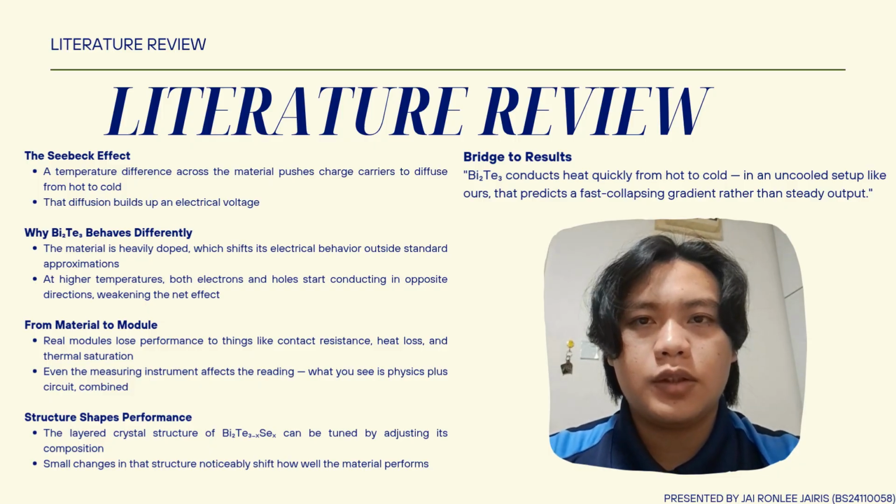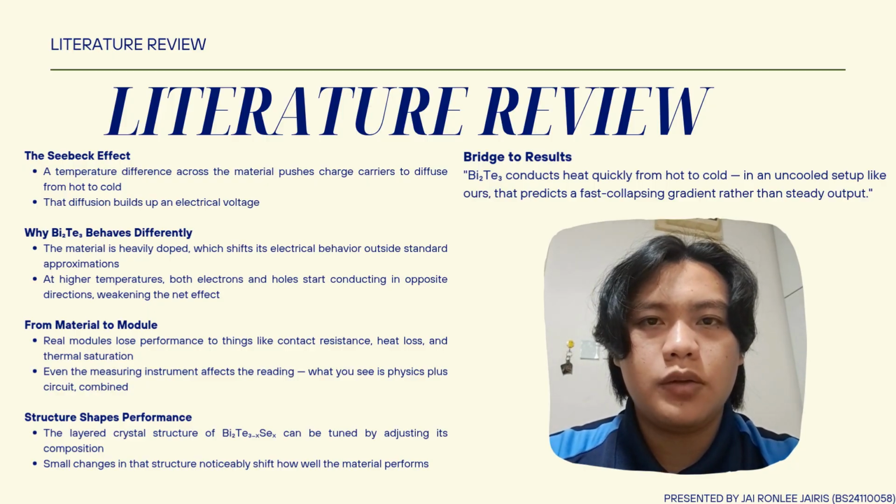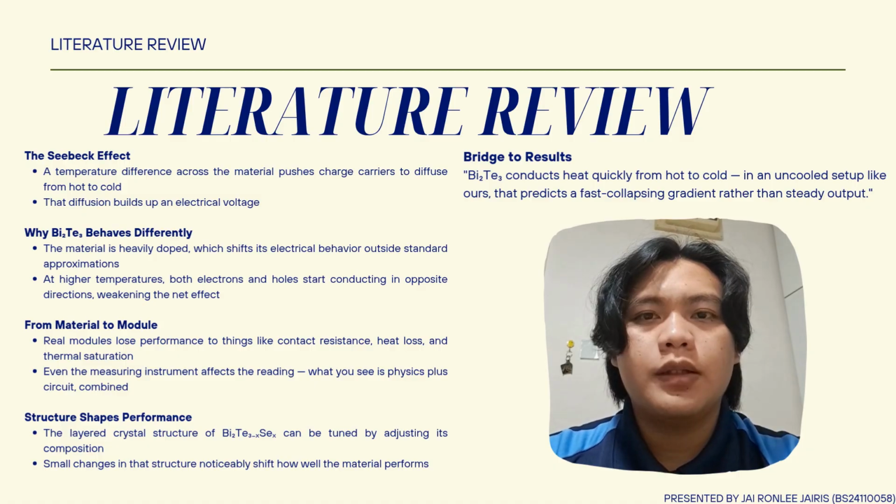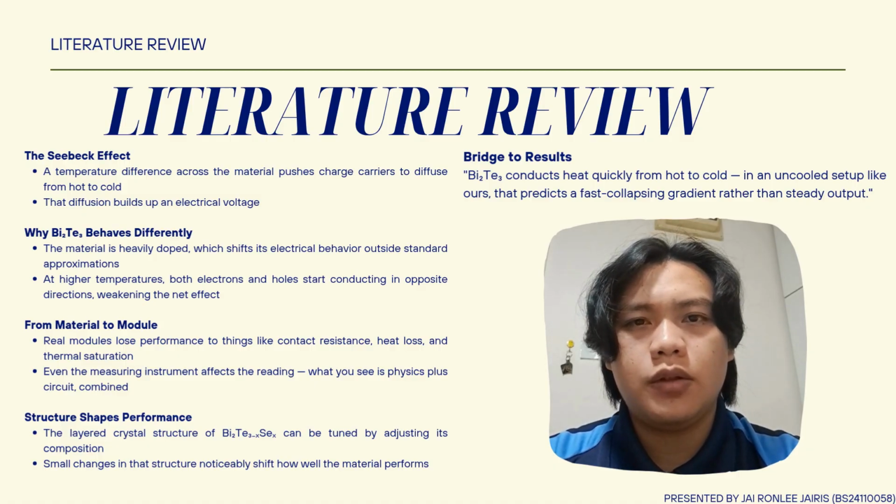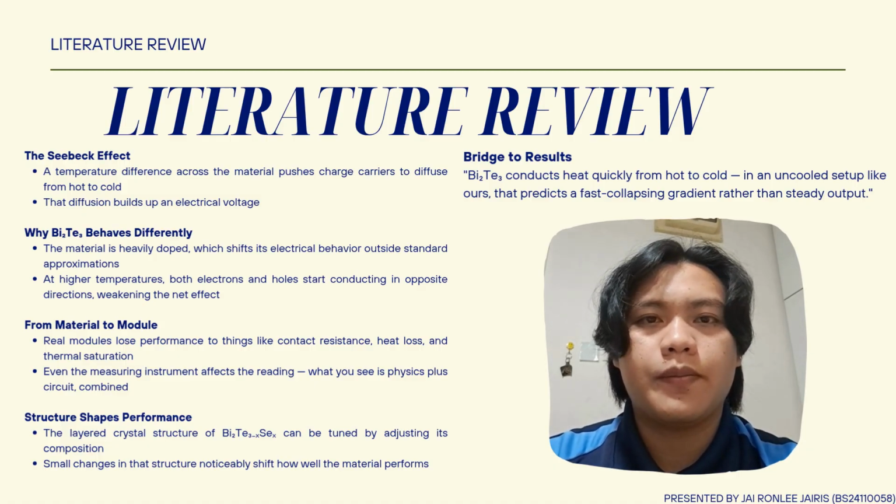Bismuth telluride conducts heat very quickly. Because our setup lacked a cooling system, the temperature gap between the hot and the cold sides collapsed rapidly. This immediate drop is exactly what you will see in the upcoming graph.